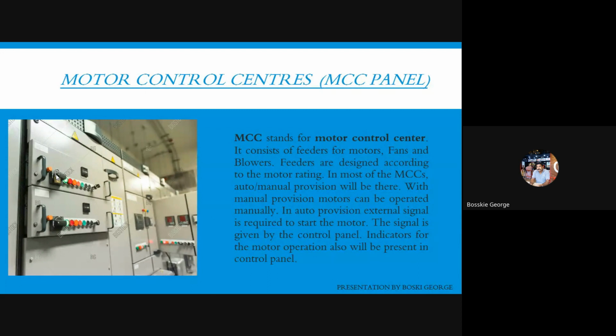How is the motor going to be started? By thumb rule, up to 7.5 kW we use DOL, and above 7.5 kW we use star delta starters. There are DOL starters, star delta starters, VFDs, and soft starters.